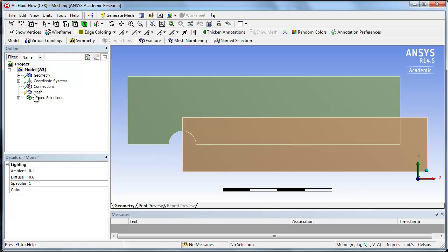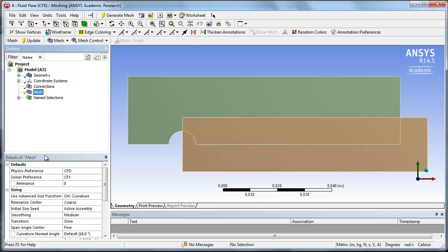And so now I need to give it commands to appropriately split this into a region of control volumes through which I can use my finite volume method for a numerical solution. So I will click on Mesh, and relevance I will move up to 100, which increases my default mesh size, or decreases it, I guess rather I should say.